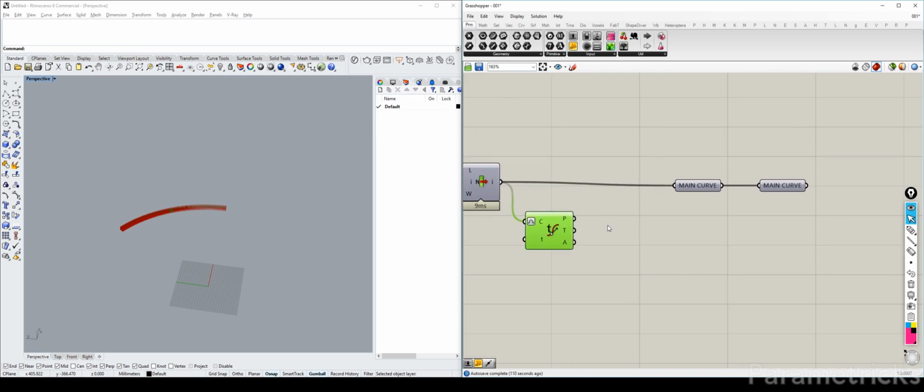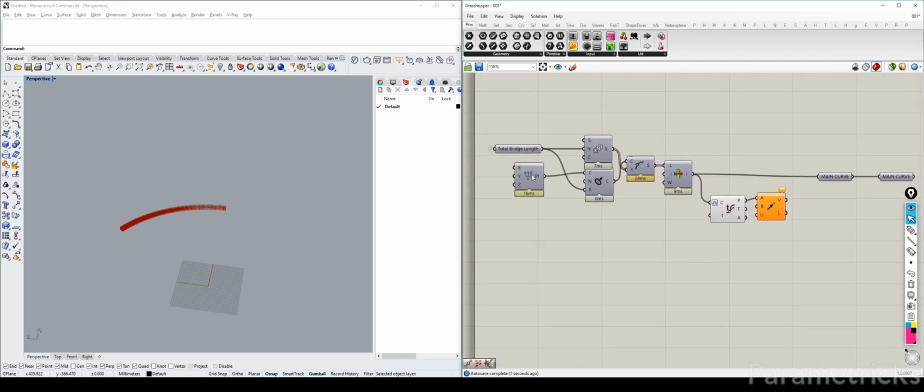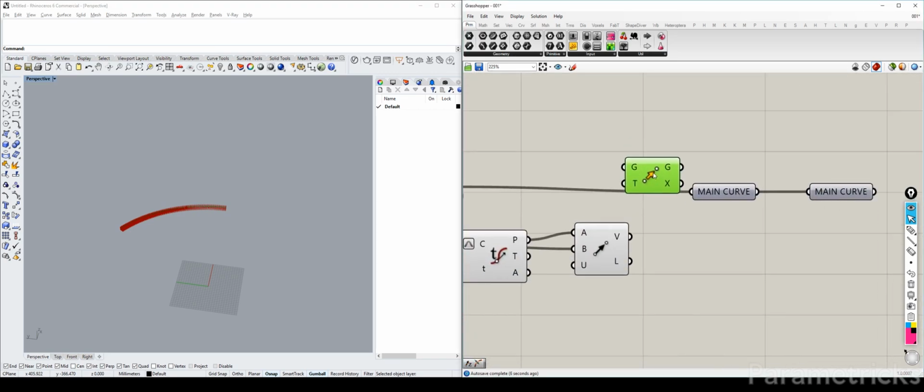Now that we have the middle point, we can create a vector, 2 points, that goes from here, and remember we have an origin point there, so we're going to use that. Lastly we move the actual geometry using the newly created vector.